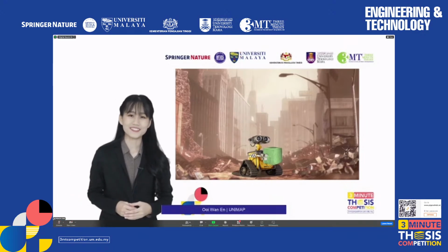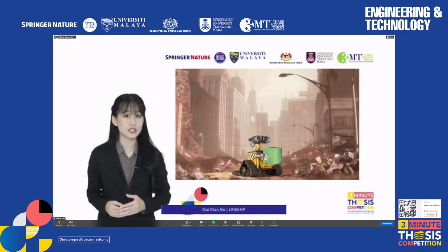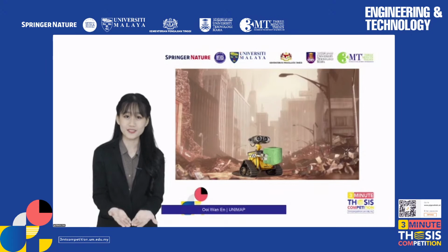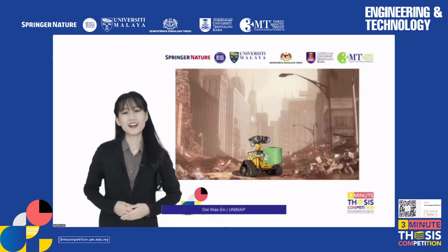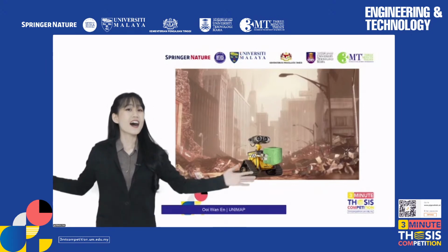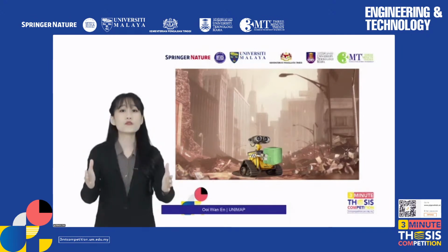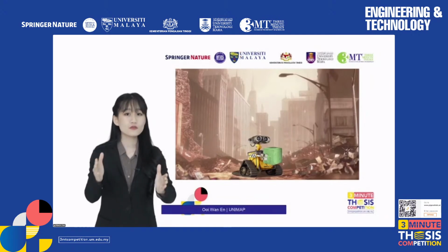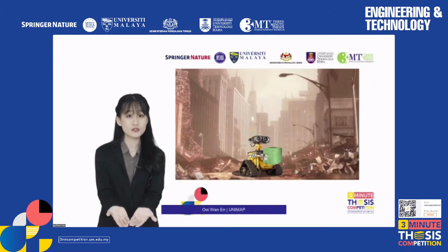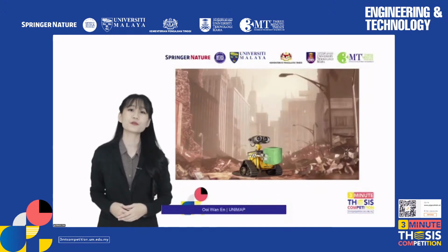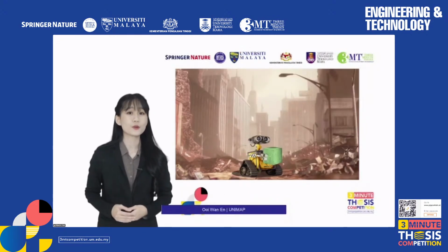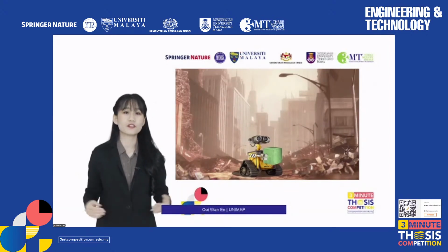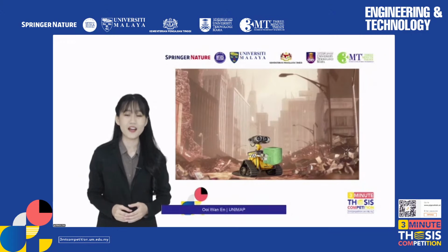So how is this material made? In the movie, the cleaning robot Wall-E collects rubbish and makes it into blocks. Well, in my context, I'm the present-day Wall-E. I collect fly ash from a coal-fired electric power plant, add some chemicals, and mix it with water to produce blocks, which is the 1 part geopolymer. Note that this material can be applied by simply adding water, which is similar to ordinary cement.